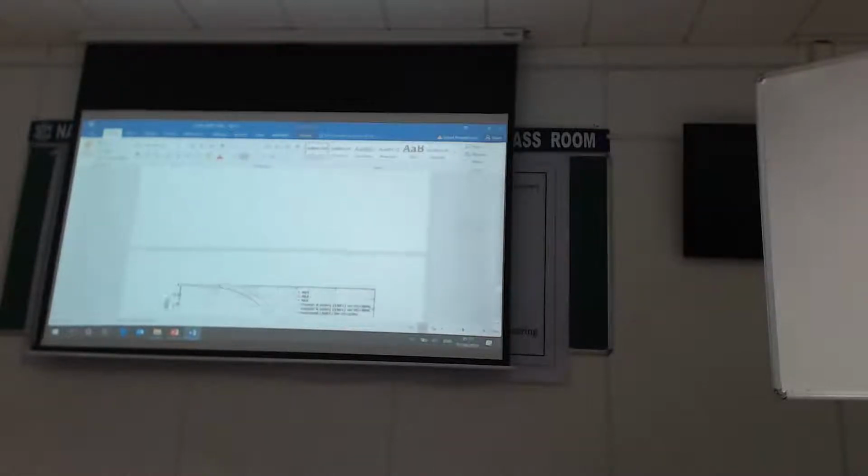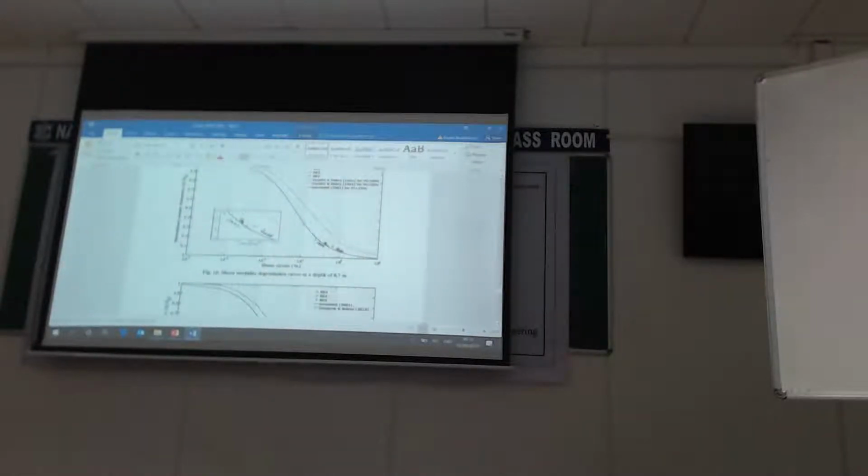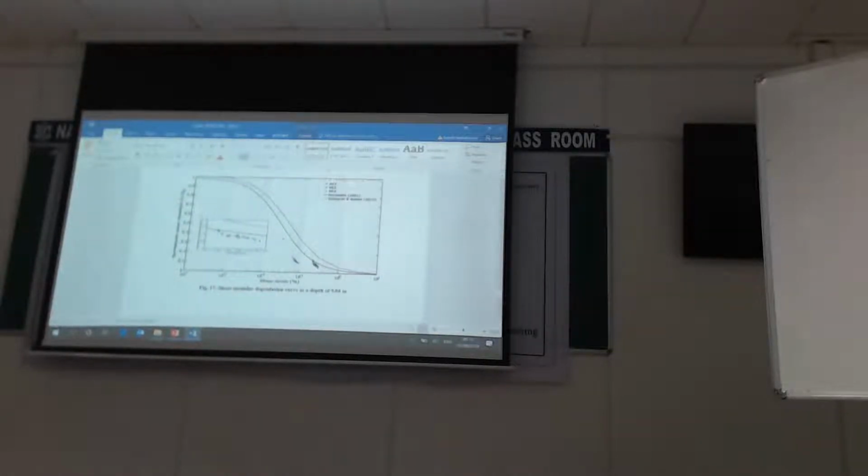So that's for 6.9 meters. We did the same for 8.7 meters, and they're all coming pretty close to the Darendeli curves. At very large depths, about 10 meters, we are somewhat deviating, especially at small strain, from the Darendeli curves. But that's to be expected because the Darendeli curves are all derived based on triaxial tests, and we are doing this using a centrifuge.